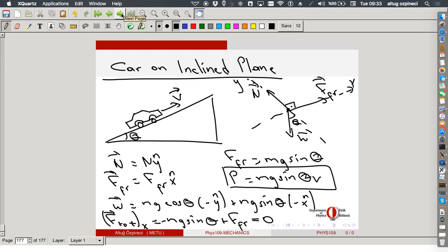If you are using a car with a smaller engine, what you do is you lower your gear. What it means is if you lower the gear, the engine will make more rotations per minute. At every rotation, the volume of the engine mainly determines how much fuel you burn. So if you lower your gear, the rotations per minute will increase, and even a car with a very small engine can go uphill at more or less a constant speed.